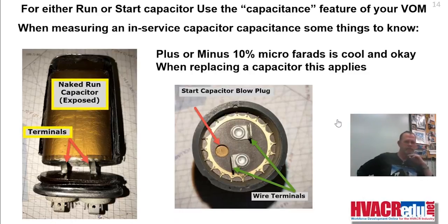We're winding down. Let's see. Jimmy, sorry, 746 watts equals 1 horsepower. Okay? It's about 3.1 amps at 240 volts. If you know Ohm's law, you can do the math for 120 volts. And by the way, those energy conversions are a real good thing to keep in your noggin, and exercise once in a while.